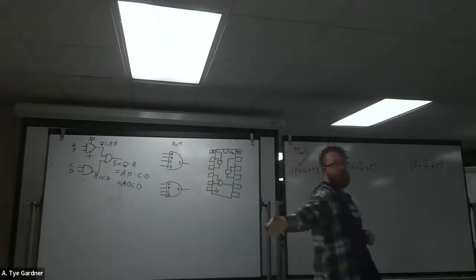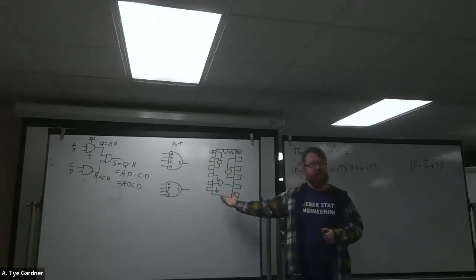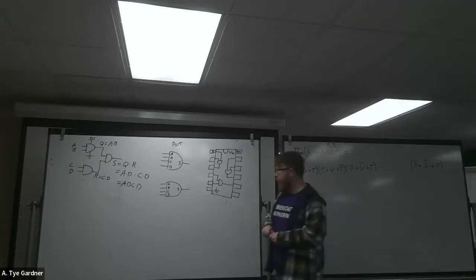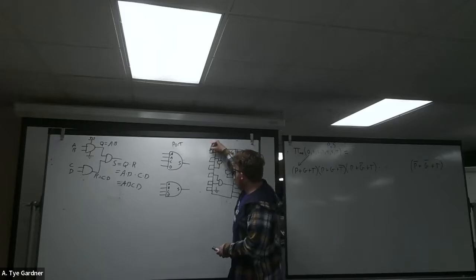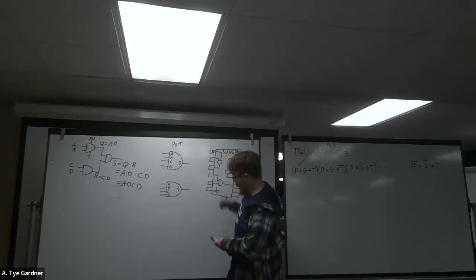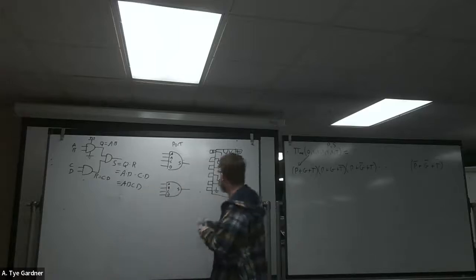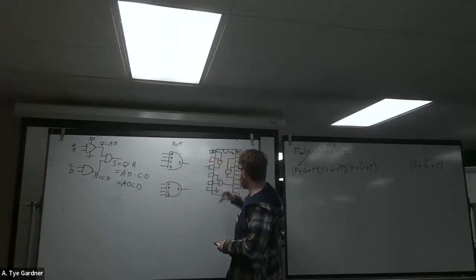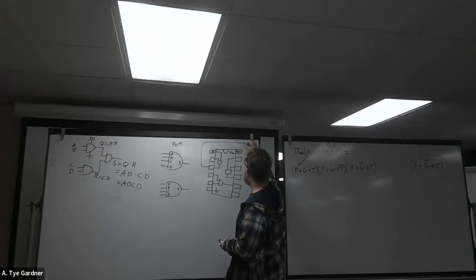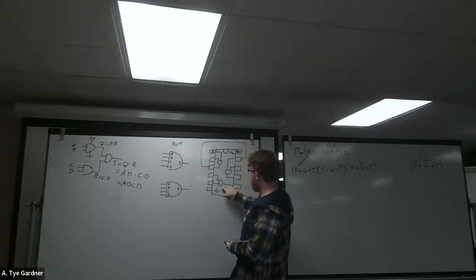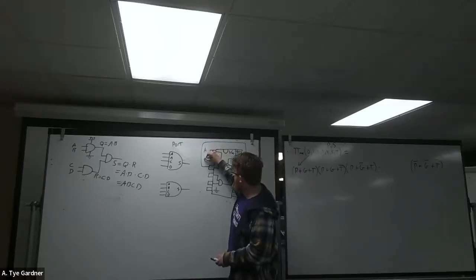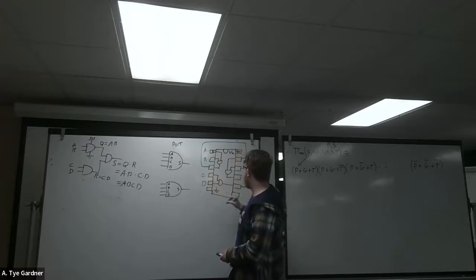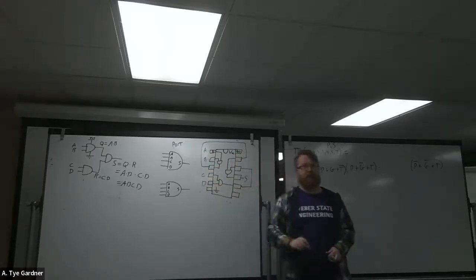is I use another one of those, right? And it's just like I grabbed another one of these out of the bin, right? We have a little bin full of electronics. You guys go and grab one of those. You throw it down on your breadboard. You hook up this signal, that signal, and then the output here goes and plugs into, well, I'm going to wrap it around and plug into that AND gate. And then this AND gate I'm going to use and plug its input here. And now I've called this signal A, B, C, D, and then this is my output S.